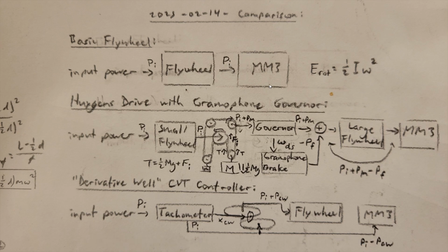The first design simply couples the machine to a flywheel via some fixed gear ratio. The machine, in this case mainly the programming wheels, possesses a moment of inertia I, but is geared to rotate fairly slowly. Hence, it will have a smaller rotational energy at its given speed. This means that for the same change in the system's energy due to the input and load, its speed will change by a greater amount.